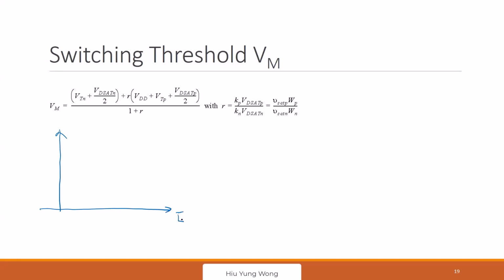If I apply an electric field, the carrier velocity keeps going up and eventually it saturates, remember? And we call this the saturation velocity. It is not a voltage. And the point where it saturates is when the electric field equals the critical electric field.